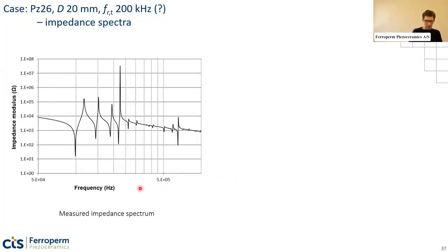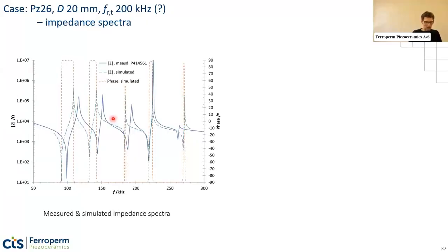Actually, this is the result, and you wanted to have a resonance frequency exactly here, but instead you basically have 3 resonance frequencies that are in competition, and none of them are 200 kilohertz as you wanted. So then we went to finite element modeling to see what was going on, and you could actually even foresee these complicated resonances by doing the finite element modeling.